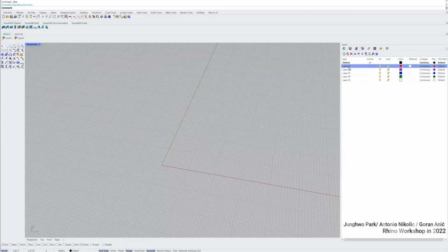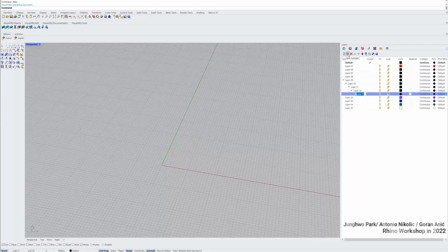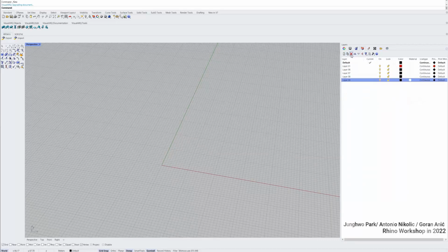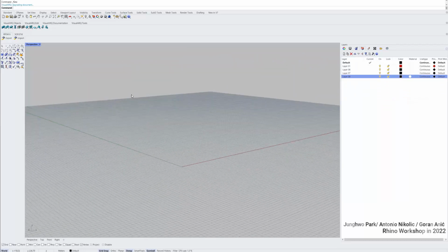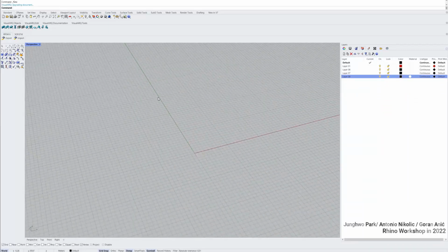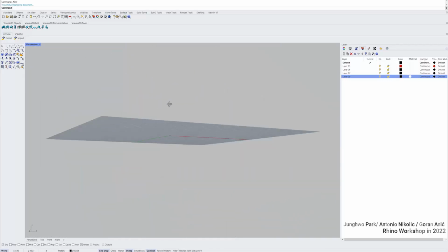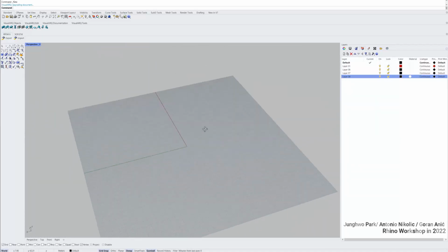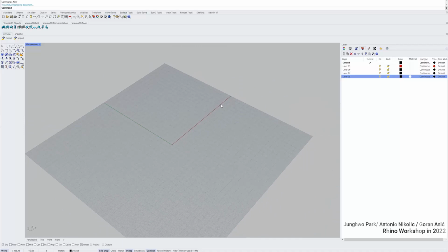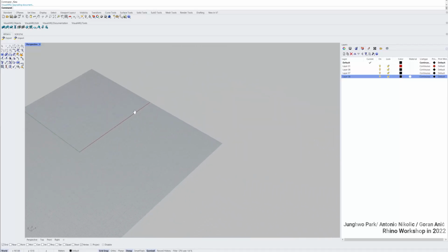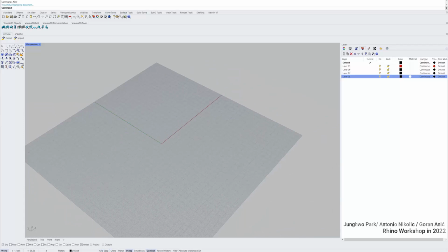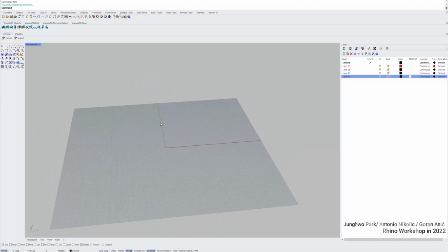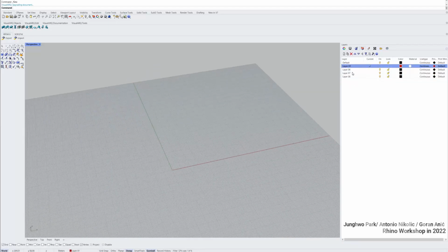We talked about how to create a new layer, how to make a sub layer, how to delete them. And also the viewport, you can zoom in and out with your mouse middle button. When you hold the mouse right button, you can orbit it. If you hold the shift key and the mouse right button at the same time, you can pan it. And we have different snapping options here, which I'm going to talk about in more detail. So that's what we did last time. We did how to select a layer, how to assign an object to a specific layer, and so on.